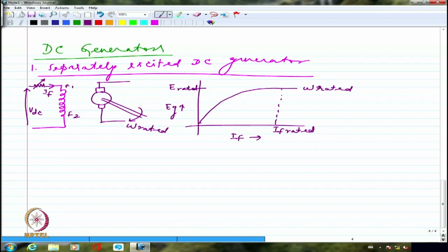Right. Now I am going to actually connect a load. After I have checked what is the value of back EMF constant and so on, I'm going to connect the load. So this is the load. Again, the load probably is variable because I want to see when I draw more current, how is the terminal voltage? When I draw less current, how is the terminal voltage? Because it will be very similar to what I had as voltage regulation in the case of the transformer.